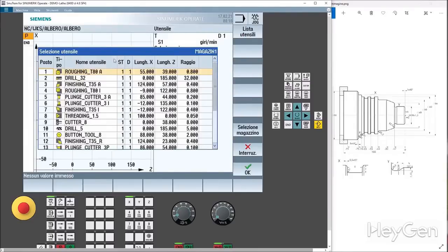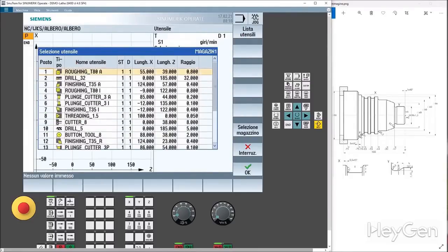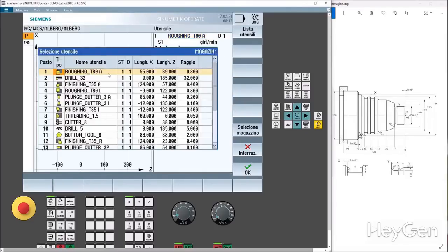The first thing you do is what you do when programming in ISO, which is to select the tool and cutting parameters. First the tool, and then tool selection. It automatically takes me to the tool page, where I've already preloaded tools in the machine that will correspond to my turret, and I'm going to create my facing operation. So I select the tool store, choose the tool, and remember that we can also add comments.